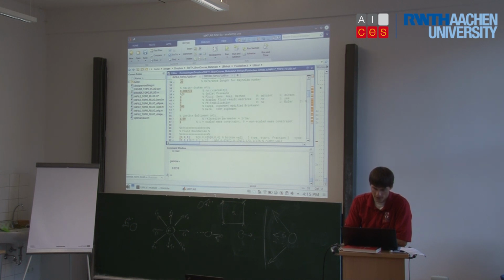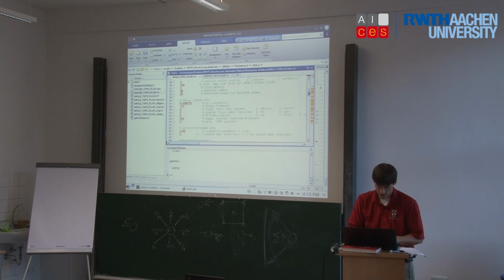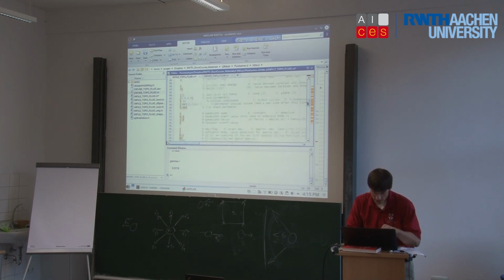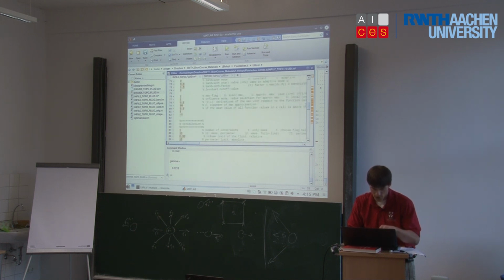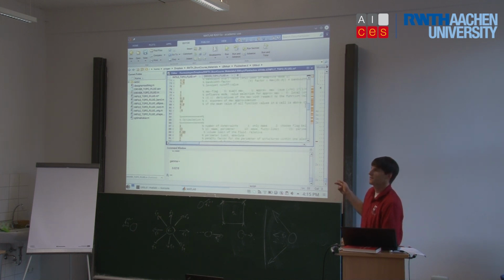This relaxation parameter is kind of related to the viscosity, but we can leave it as is because we're looking at Reynolds number. As long as the Reynolds number is fine. Let's see what other settings we have. These are level set settings, so they're irrelevant at this point. Now the important thing is when you change this function, this is the input file, you don't want to delete any rows even if they're empty. There's a read function that reads from this file into Matlab variables, and if you delete a line, it's going to offset everything.